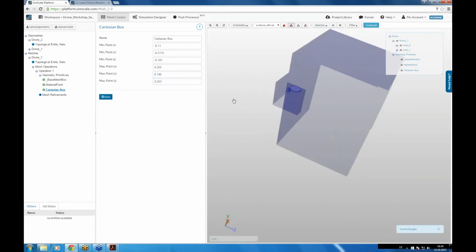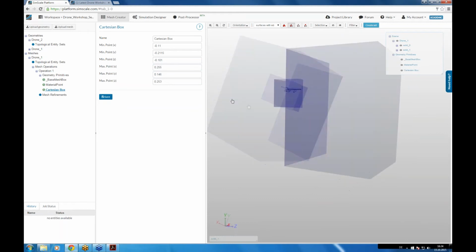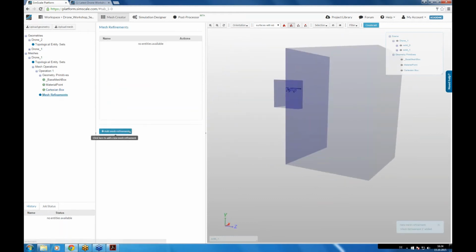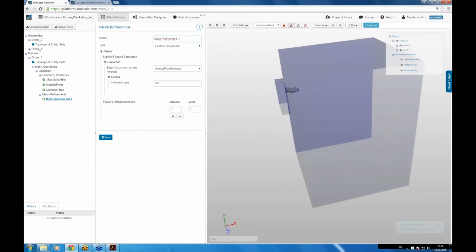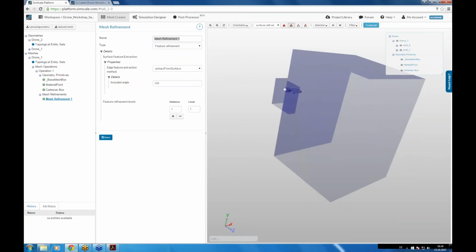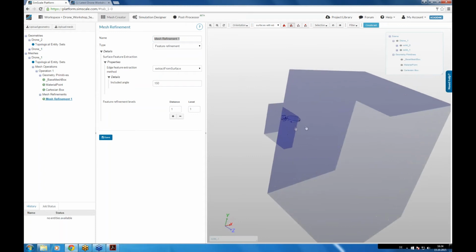And now we have an additional refinement zone where we can refine the mesh and the elements. And now we are nearly finished. Now we are really at the point where we're defining the actual refinement. First of all, as I mentioned, we have this zone, this cylindrical volume, which we will later use to define the rotation of the air, because the air is rotating around the propeller, and this has to be defined in the simulation manually.